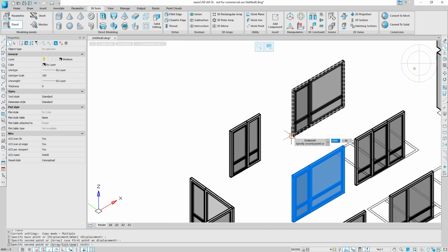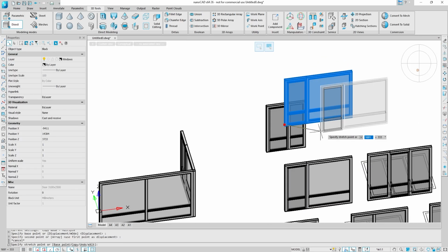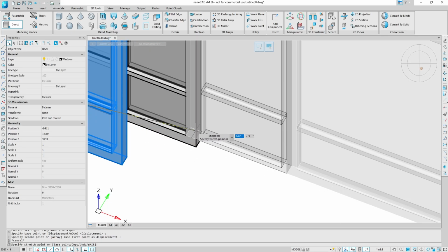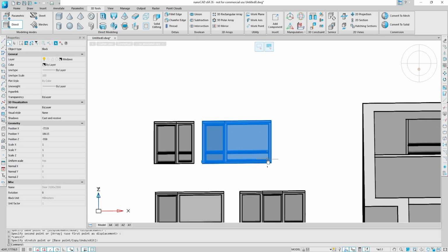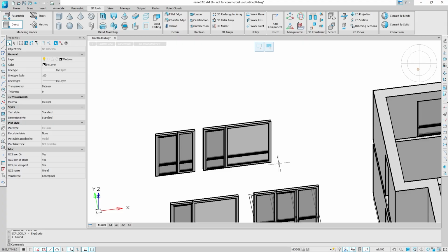Create the 3 remaining doors for the second floor yourself. The first door can also be modeled using the Slice command, having previously reduced the length of the frame by 500 millimeters.